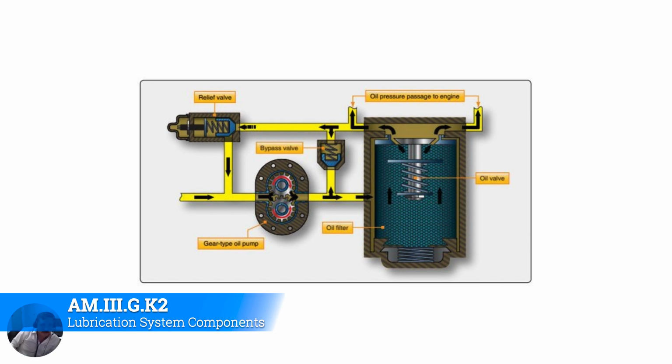The relief valve basically means that, hey, look, it's going to spew oil outboard if it goes, whereas the bypass valve keeps it inside of the system. It just allows it to bypass whatever is clogging it up.